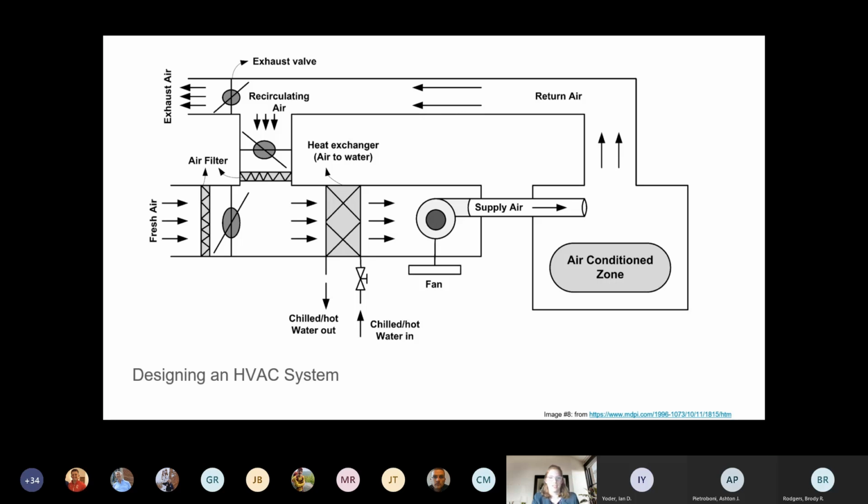If we turn our attention to the schematic, it is clear that there are many detailed components at work in the air handling unit. Starting at the bottom left, the system takes in outside air and passes it through a sequence of dampers, valves, and air filters before it reaches the cooling coil. Once the air reaches the desired conditions, a supply fan drives it into the zone, a zone being a single conditioned space controlled by a single thermostat.